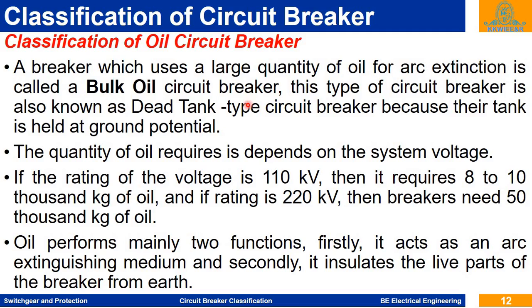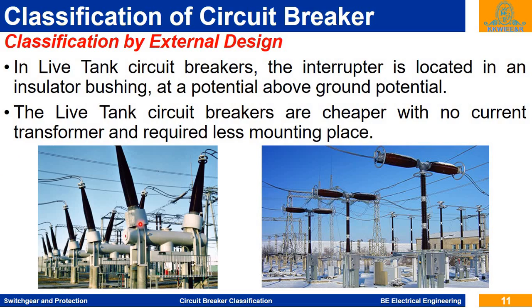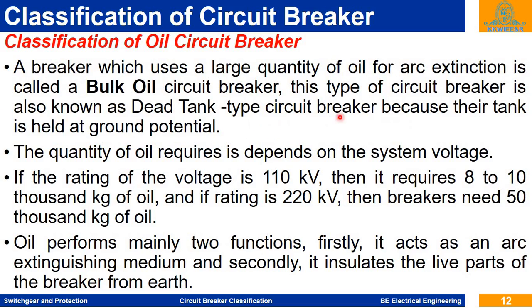That is called a bulk oil circuit breaker, BOCB. As you can see here, bulk oil circuit breakers are also called dead tank circuit breakers, because this oil tank is held at ground potential. Depending on the voltage system, the quantity of oil required changes.